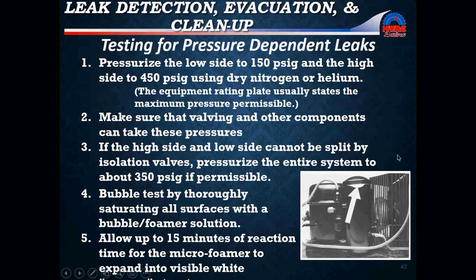Allow up to 15 minutes for reaction time for the microfoamer to expand into visible white or any sort of bubbles. Like you can kind of see here, this receiver right here is actually leaking. You can see this little bubble right here. Check welds around the compressor. I have seen that a couple of times where the actual weld on the compressor was no good and it was leaking right there at the seam.